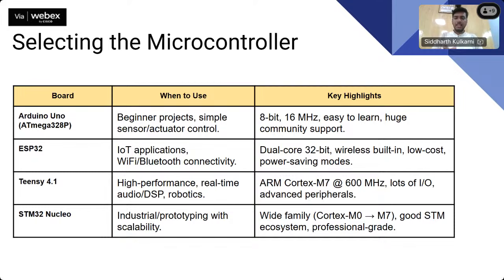Something very similar like that can be easily handled typically by an Arduino Uno. If you have something that requires IoT applications, like you need Wi-Fi, Bluetooth connectivity or some kind of wireless activity, you can then look towards ESP32. If you need some kind of high performance microcontroller, let's say you have multiple motors, multiple encoders, multiple sensors connected, and all of them are a bit heavy to compute, then Teensy, STM32, etc. can be a good option.